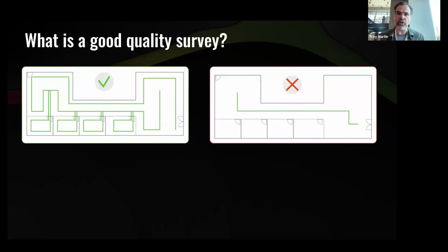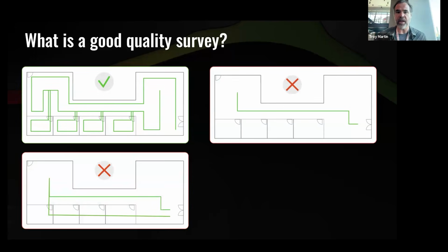So some people will cheat and say, hey, what if I just walk down a hallway, right? I'll measure the signal. And I've seen the software where it kind of guesses or extrapolates what the signal coverage is like that. And that's true, the software does that, right? But it's like working with an arm tied behind your back, right? All we can measure and extrapolate is signals that we've heard. The software doesn't inherently know that there's a wall.